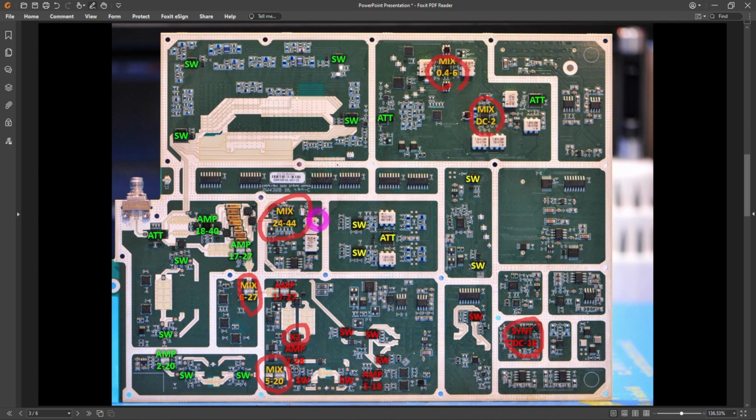And if you look at the block diagram of this, I'll put it on the screen. This actually has a built-in ×4 frequency multiplier. So the combination of the internal multiplier of this one, the external multiplier over here, and the synthesizer will basically cover all the frequency ranges. And the reference to the synthesizer comes from the other board, which is a DDS, which is a 1 gigahertz DDS, as we will see.